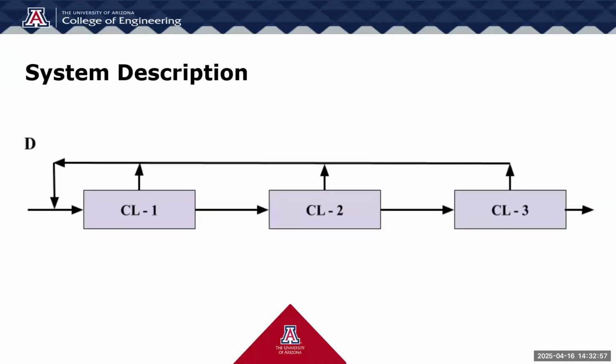Exhibit D combines both cascading and recycled air systems. Like Exhibit B, each cleanroom sends only the required air to the next one, but the excess air is sent back to Cleanroom 1 and mixed with incoming fresh air. In Cleanroom 3, the ratio of exhaust to recycled air is 2:1.